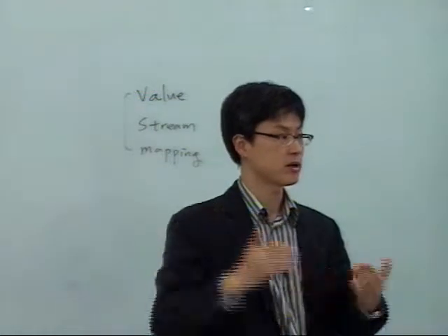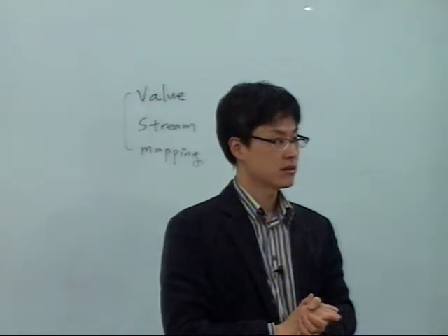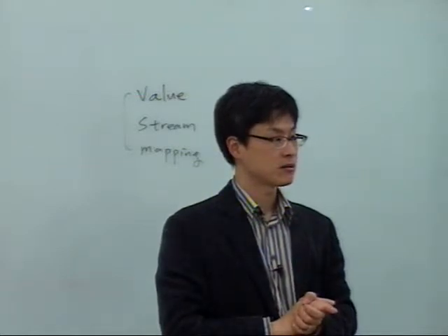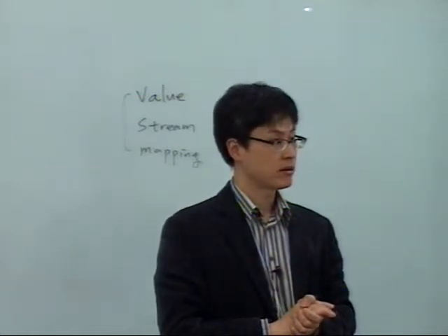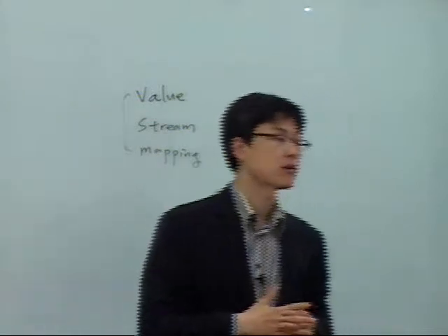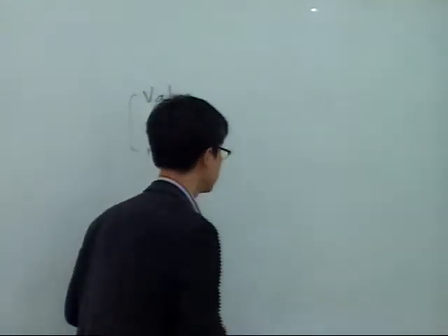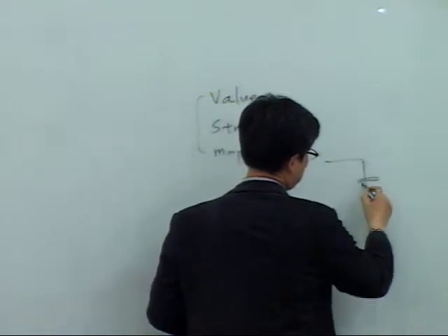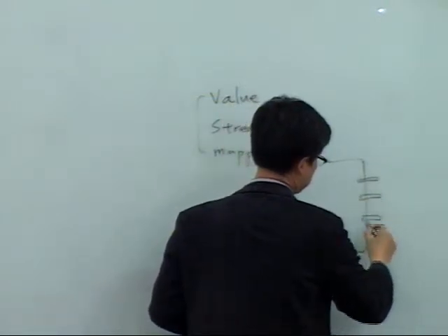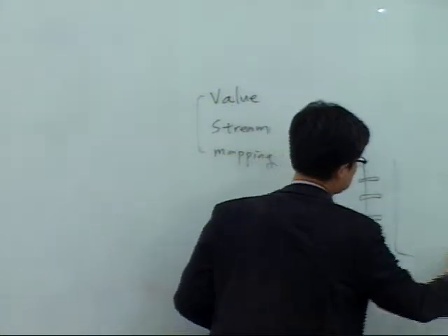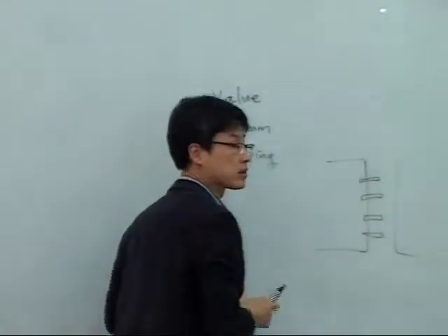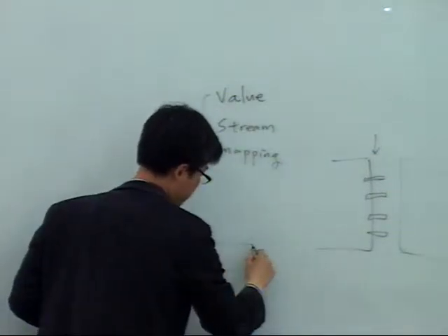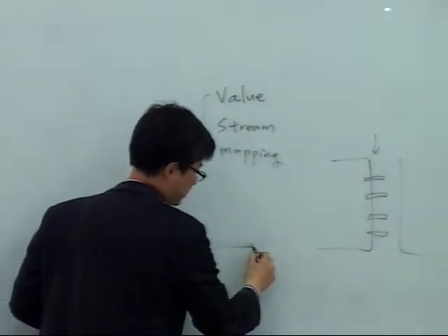Think of the overall size: 20 meters over 2 millimeters. It's 10 to the minus 5 accuracy. Very, very hard to do. So people tend to add some kind of guides like that. Block A, block B. If you look this way, this guide looks like this.